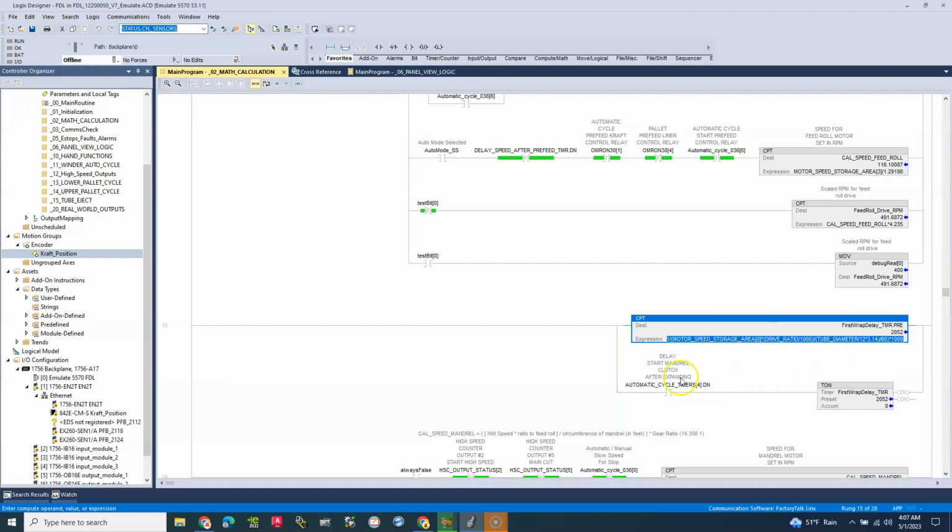That's important. All right, now a couple of other things to consider in this equation, right? So we have our speed, we have our drive ratio, which is a data piece entered. We have an equation here, a constant of 1000, right? So that would determine how many revolutions, right? And that would lead us to our encoder. We'll get to that in a minute. We have our tube diameter, and we're breaking it down here, the diameter divided by 12 in inches times pi, divided by 60 times 1000.